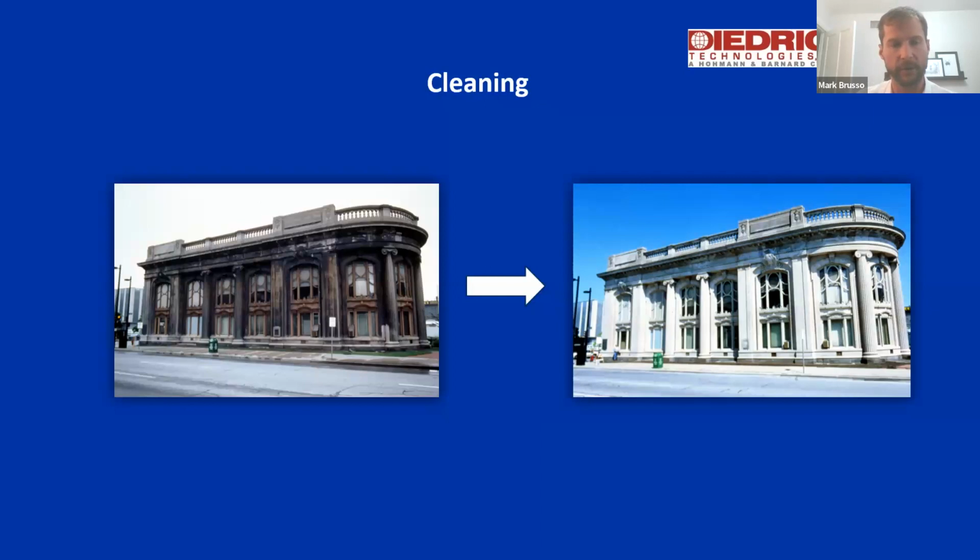cautious. And I always recommend before starting any cleaning project, because a lot of times there's a lot of unknowns with how things are going to react with the method of soiling and the backup and the chemistry of the actual material, to always do a mock-up, as you would do a mock-up on a job site of your detailing and your window projection. So always try a mock-up on an area of the building.